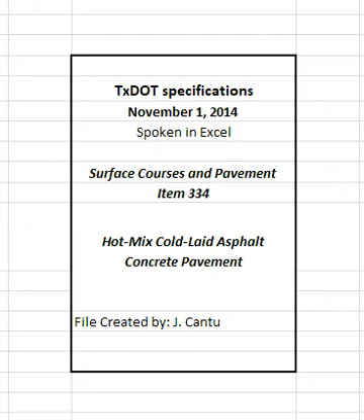The aggregate gradation of the number 200 sieve may not exceed the master gradations shown in Table 4. Any sieve size shown in Table 4 with 100% passing requirements will be allowed a 2% tolerance before the material is considered out of specification.